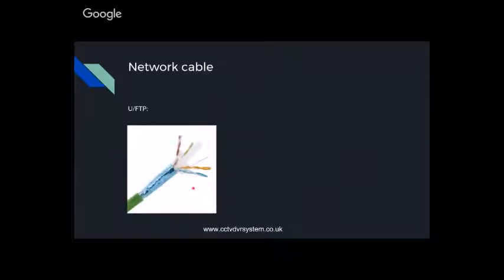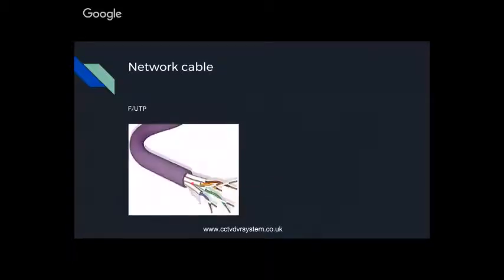So just to give you more idea about shielded and unshielded, or FTP and UTP. Now, you see that it's got a screen protecting all the cables, it's got a separator, then you've got the 4 different twisted pairs. Whereas if you find this picture, you have different screening for different pairs. So the pairs are well protected within the sleeve. So we call it FUTP.